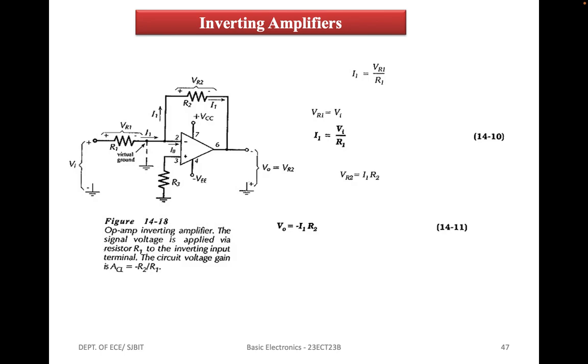Any increase or decrease in the difference in voltage between the two input terminals is amplified by the op-amp open loop gain and fed back via R2 and R1 to correct the change, because the inverting input terminal is not grounded but remains close to ground. The inverting input terminal in this application is termed a virtual ground or virtual earth.